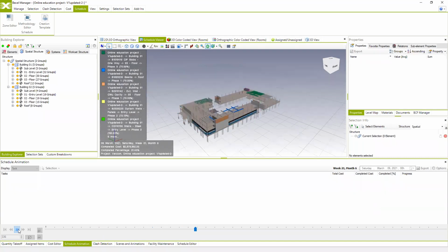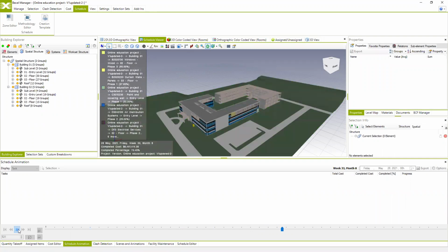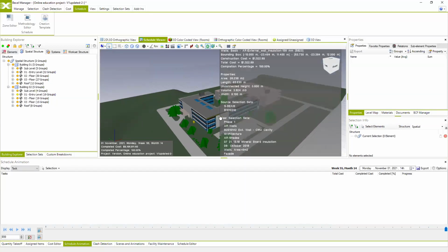So once you create your cost classification and your cost estimation, with specified resources, you can define your methodologies based on classifications and cost items, and then the system will automatically create the entire schedule with hundreds of tasks and the relations between these tasks, and everything will be related with the resources based on available quantities and resources extracted from the BIM model.